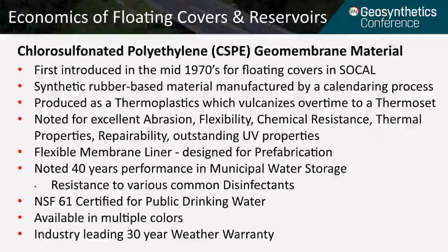And it's noted for its excellent abrasion, flexibility, chemical resistance, thermal properties, ability to be repaired, and outstanding UV properties. It's defined as a flexible membrane liner designed for prefabrication and flexibility. And it's become noted over the last 40 to 45 years in municipal water applications, and its excellent resistance to different types of disinfectants, including chlorines and chloramines.